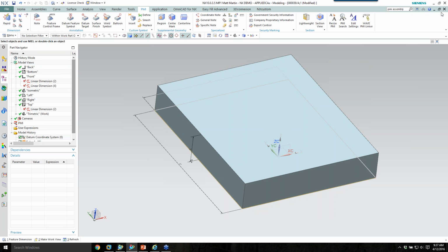Okay, I have another question. If you've got the tolerances applied using PMI and you give that file to the CAM person doing the machining, is there a way, like I'm thinking about our gauging where it uses an MMC model, but right now we're physically modeling that MMC model. Would there be a way to use the PMI and a nominal model such that the geometry could be machined to a maximum material condition? That's a good question. I'll have to get back to you on that.